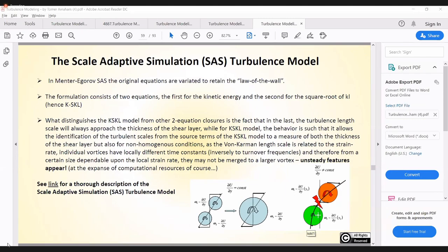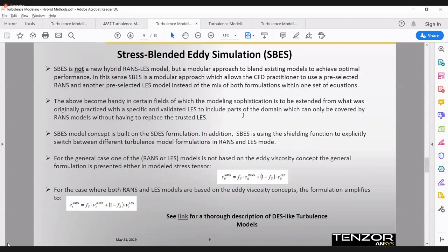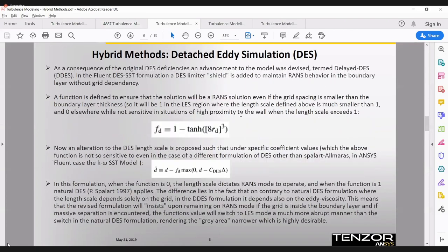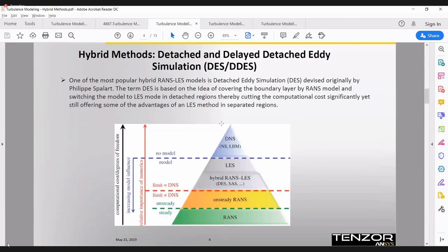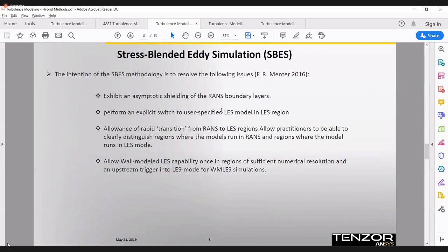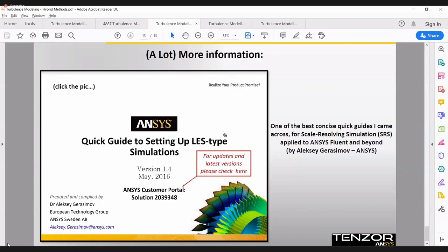But if I now open the best practice for large eddy simulations, what I would have to see is that I have to check higher moments and take the PSD and check it, and not only check that I see some nice Q factor lying around.